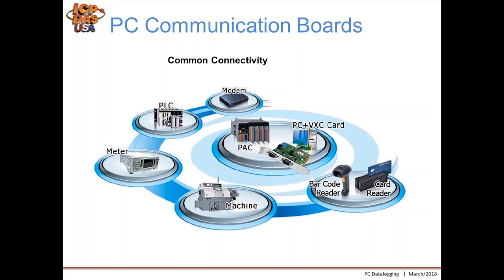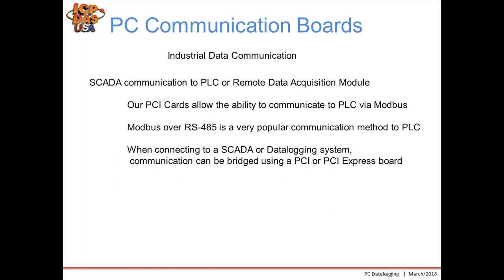The other application, again, is industrial data communication, which a lot of our products are used for these applications. SCADA communication to PLCs or remote data acquisition modules. Again, the PC communication boards can be used to communicate to our remote data acquisition modules with protocols. These are different from the PC cards with the I/O that we talked about earlier.